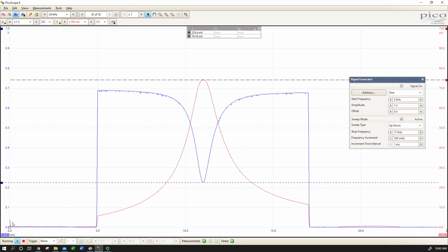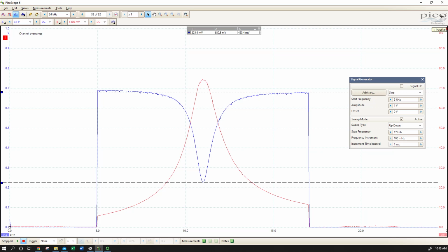But we could at this point stop our data collection and stop our sweeping. And we could go ahead and use two different methods now of measuring bandwidth. We could again do it like we did earlier in our recording on the full circuit. And for this, I would take an average of the total voltage drop over the circuit well away from resonance, both on the high and low frequency side, and then of course, my lowest voltage drop.